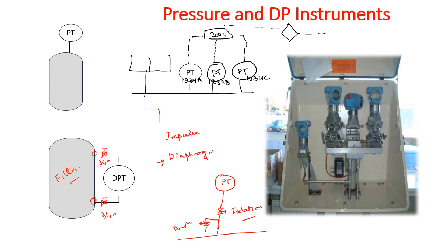Only one major concern is that sometimes in the P&ID, root valves are not shown or are not shown correctly. So you need to check other drawings like isometrics or the detailed hookup drawing of the instrument to understand in more detail what the different components are, because the P&ID is a little bit high level. So if there is a small valve in the impulse piping, many times it is not shown in the P&ID.